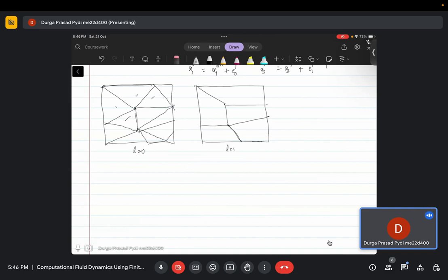You have to update all your secondary gradients and all of this again, and that is quite a lot, it might take a little more time to do all of that. So you can increase it further, you can take a single cell like this into 2 more cells, and the last step is essentially to get 1 cell. But how do you know which one of these ways? This is not the only way to go to a coarser mesh. You can go in 100 different ways.